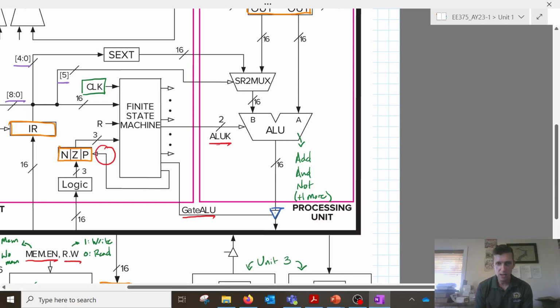So what I've got down here in blue is something called a tri-state buffer. This is a device that will either allow the ALU result to pass through and drive the processor bus high or low, or it will float, meaning it will have a middle value that lets another device pull the processor bus high or low. So you'll see this all over the LC3.